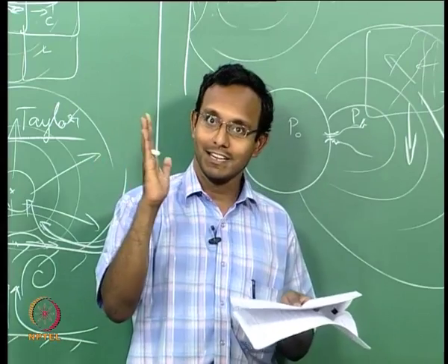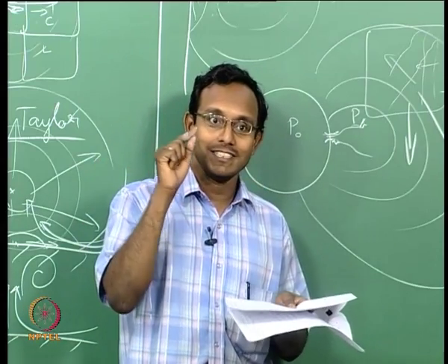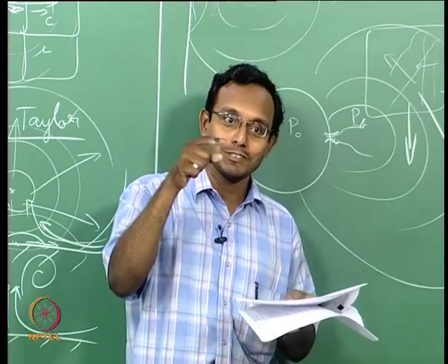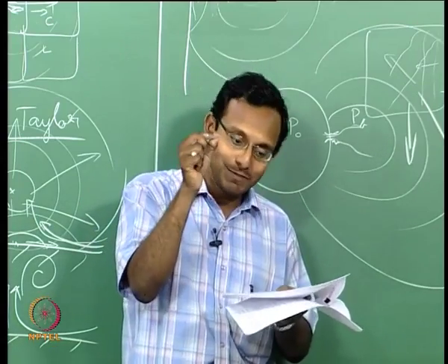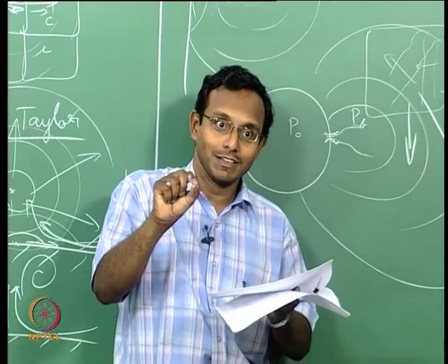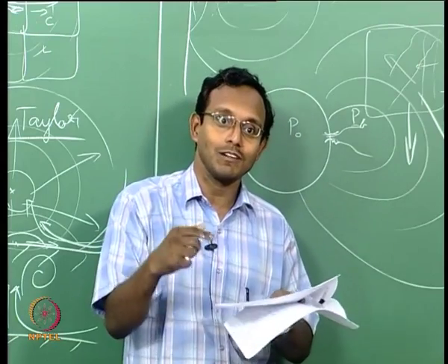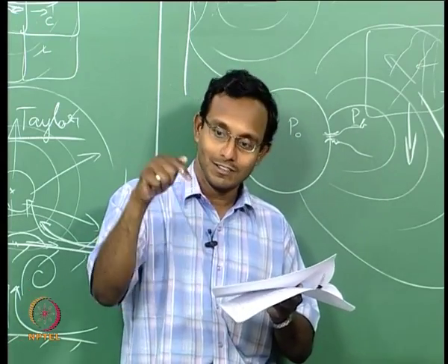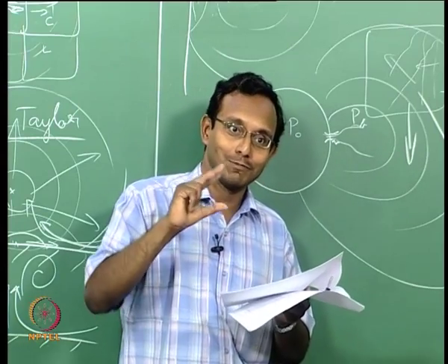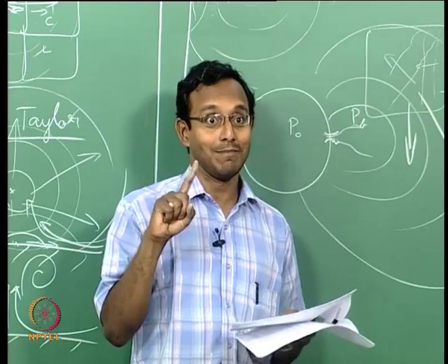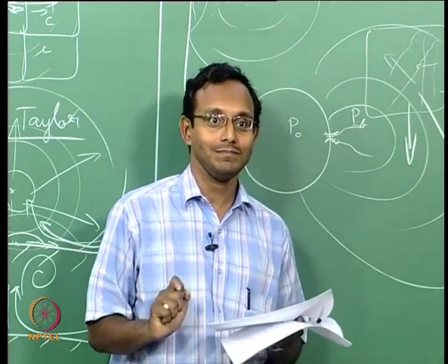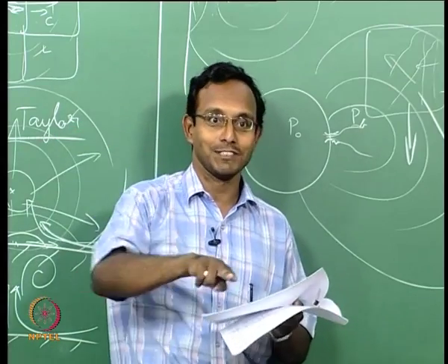And while it is moving, it is sending that energy into pressure energy. Pressure waves are going in all directions, but some of them are bouncing and coming back to this wall. When it comes in, it is getting bounced back against a moving wall, which is becoming even stronger. So it is going up and down, getting stronger and stronger and stronger. Eventually it gets much more compressed, while at the same time on the side it is getting expansion waves from the outside. Outside is sending expansion waves to the center.